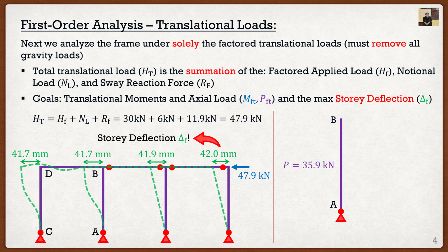foot a little bit, because this tension is actually going to decrease the loads in our column, which is a good thing as designers. We want to try and have the smallest loads possible, because then we have a cheaper design. As you guys have probably picked up by now, it's all about money in structural engineering. So the cheaper the design, the better off you are. But remember, axial load is just one of the two things. We also need bending moment.